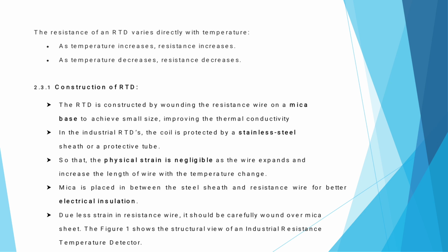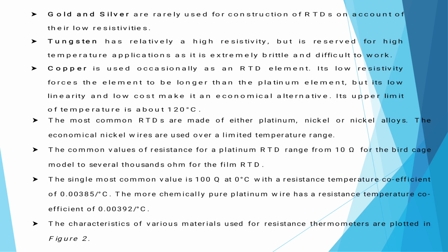In fact, when we constrain our operations to relatively short temperature spans, this linear behavior becomes even more evident, and this simplifies our data acquisition and signal conditioning requirements, as the higher-order non-linear terms in our polynomial equation leave a stable and direct relationship. So the straight-line mapping can be simplified here.